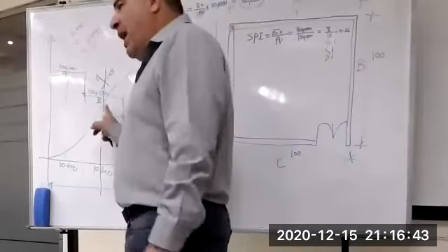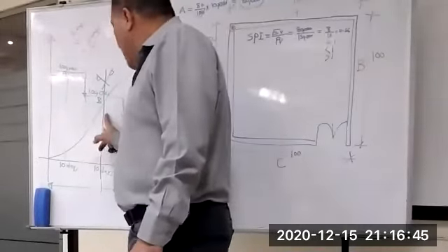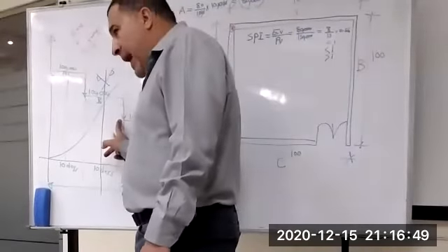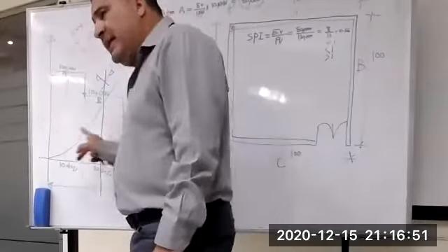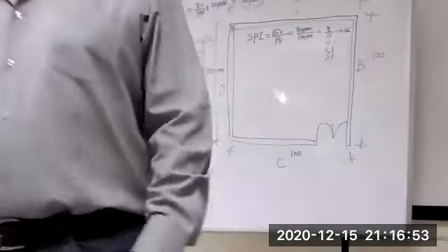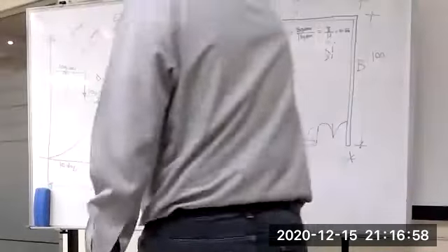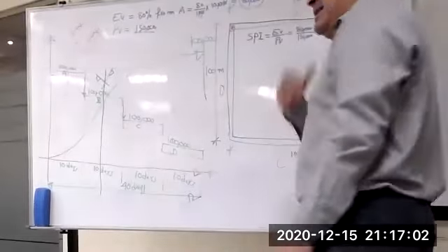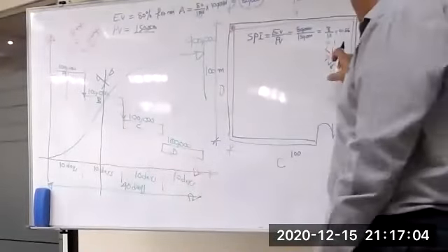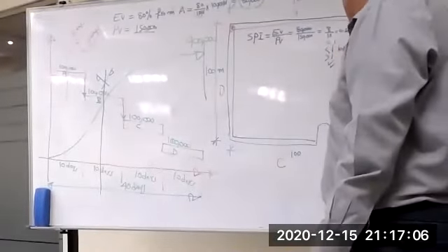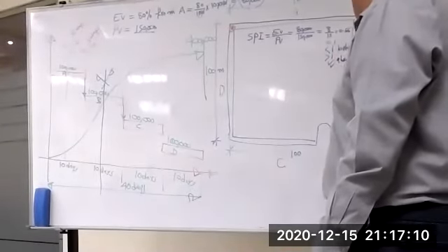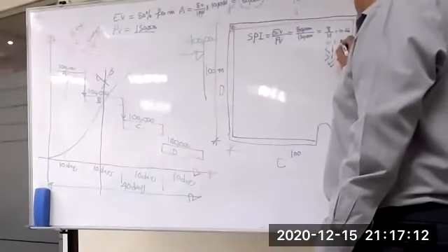In day 15, you finish 60% of B, that means 60,000 plus 100, you already finished it, you are 160. 160 divided by 150, you are more than 1. You are now ahead. Less than 1, behind. Equal 1, as planned.